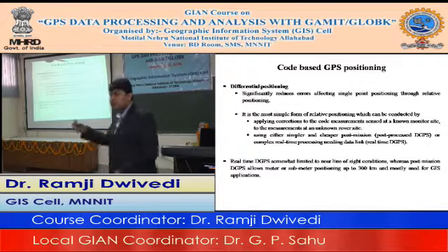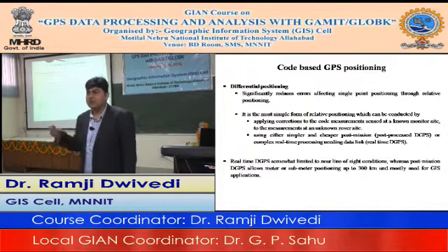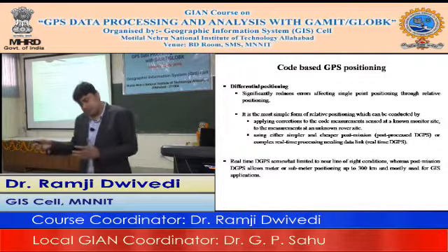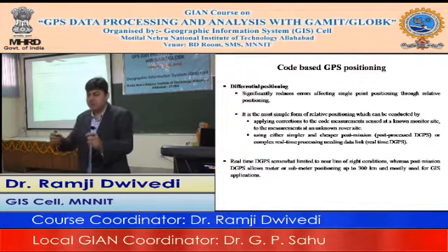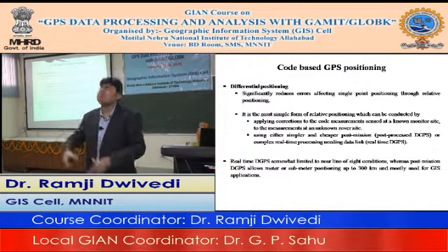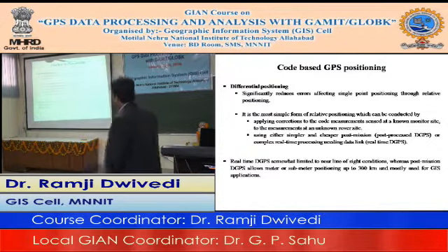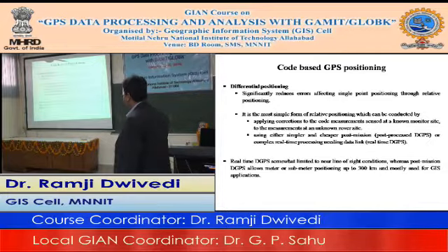When we did the DGPS experiment, the industry people came for training purposes and showed us the picture where the radio modem at the base station was established on the rooftop, so that the line of sight would be clear to the rover stations. Okay, so sub-meter positioning up to 300 kilometers or maybe less. This is for the conditions which are favorable to DGPS.